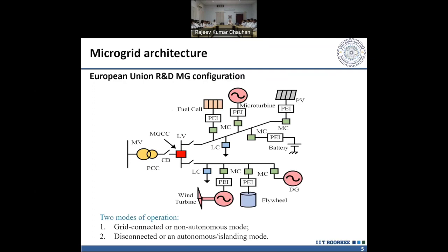How to integrate a solar power plant with 132 kV? It will be very difficult. You have the DC, convert DC to AC first, then step up to that level, and only then go for the integration. So that's why we say renewable source integration with the grid is still a very big challenge.